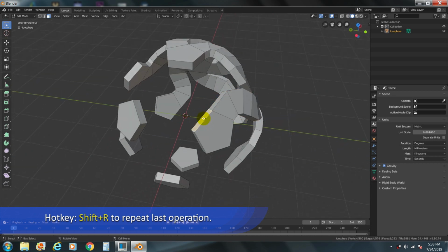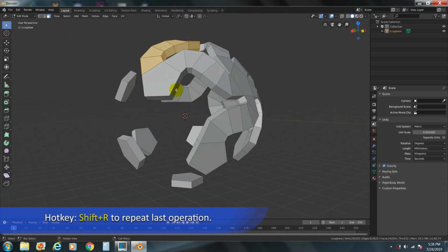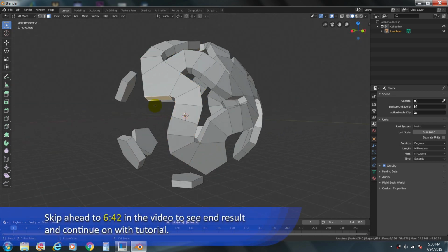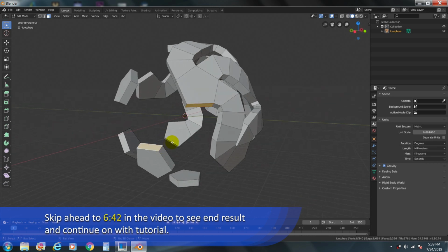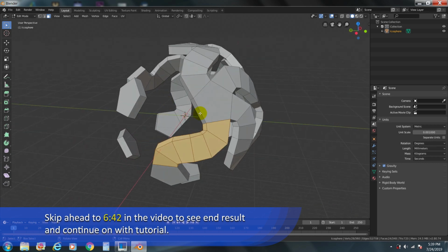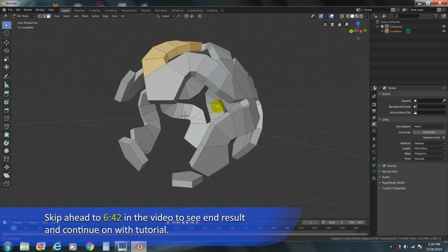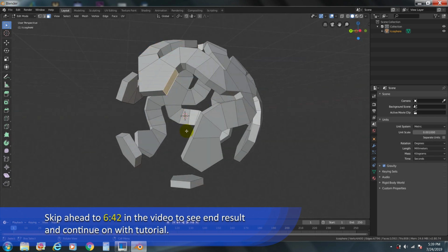Once again, the key to this entire process is to simply work from one pentagonal element at a time, and follow the vertex to the right of your selection directly across its normals to the mirrored element, and select the polygon whose normals would run parallel to your current selected face. If you think you've got the hang of it, you can just skip ahead to the part of the video where the process is completed.